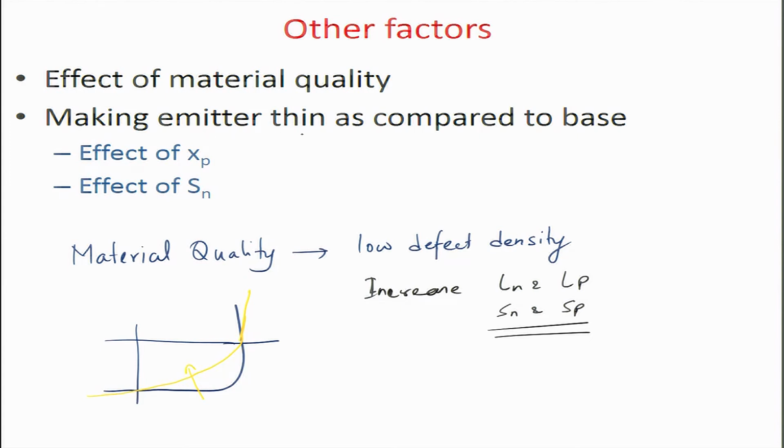And another thing which is quite commonly talked about is in the silicon context. In silicon, generally the top layer is called the emitter, we will see this later on, and the bottom layer is called the base, and this top layer is generally P plus, and this is N layer. Oh, sorry, this is N plus and this is P layer, I am sorry. So this is an N plus P kind of junction.